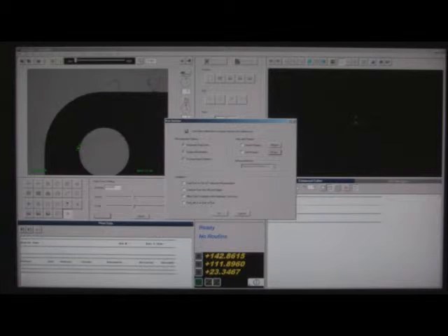We can also put some conditions on the part. I can tell it to stop if we measure something out of tolerance, or continue to run if it misses a feature. If a feature is missing, do we want to continue and just put some arbitrary number? I can put all 9s as a result if a feature was missing, rather than have the program stop. I can allow step completion after minimum data entry. What minimum data entry is: for a circle I need 3 points. I may have used the strong edge circle where I told it 10 points, and because the feature was bad or it couldn't measure the edge for some reason, do I want to go on after those 3 points?